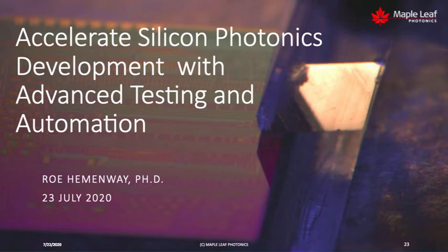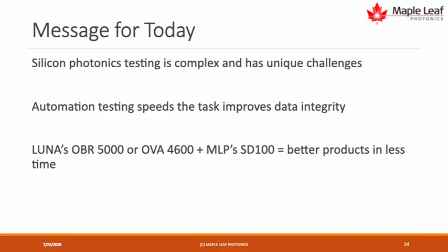And the emphasis that we would like to establish here is that the earlier you do this in your fabrication process and in your development process, the more insight you get into the role of fab variations. As Brian pointed out, Silicon Photonics in particular is very statistical in nature. 50-50 couplers are only 50-50 if the fab is correct. And the idea here is to get as early a view as you can of the performance of the circuit and ensure that any subsequent processing you might do is also maintaining the fidelity that you got up front.